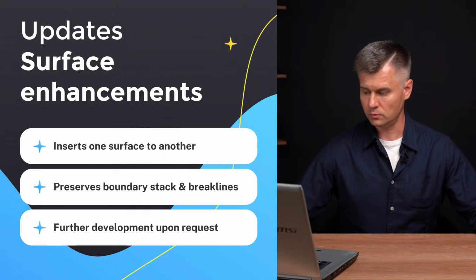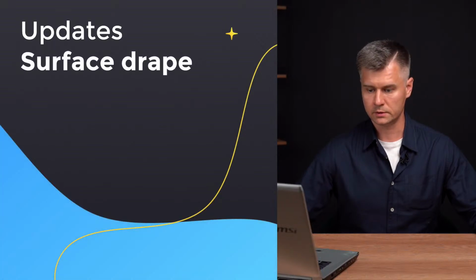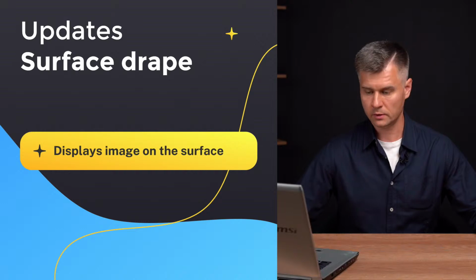Okay, so let's move on further, and the next improvement, it's the surface drape. We are working on visualization support of draped thin surfaces. This feature allows displaying an image on the surface, for example a geo-referenced image, and to use this feature, switch to realistic mode and enable the display of triangles in the surface style components.